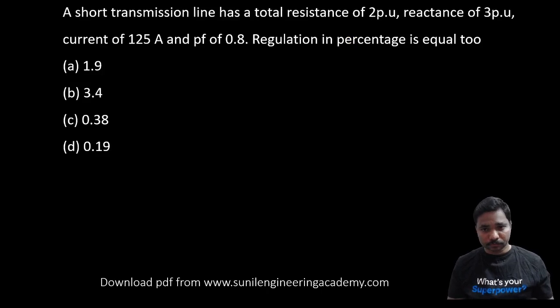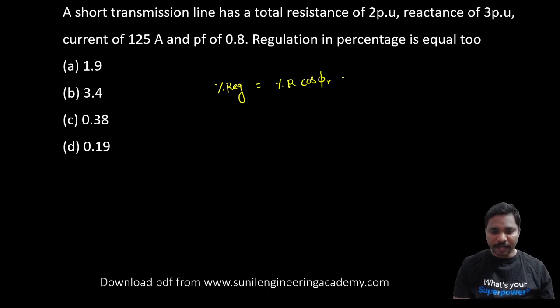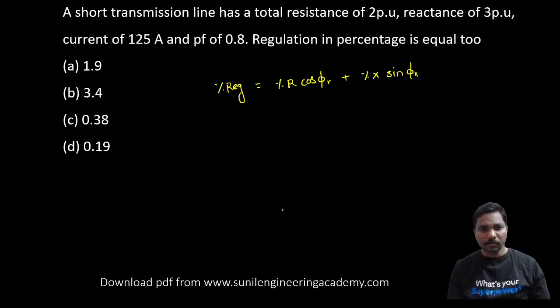Next question. Here they have given regulation in percentage. We know very well the regulation formula. All of you try to remember: percentage R cos phi at receiving end plus percentage X sin phi at receiving end. Okay. R cos phi plus X sin phi.